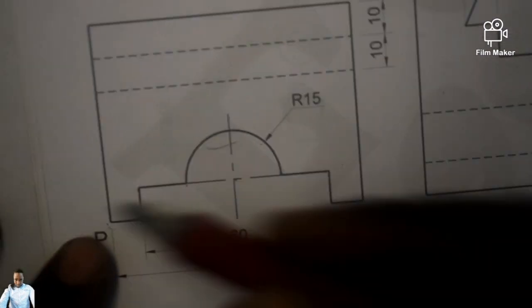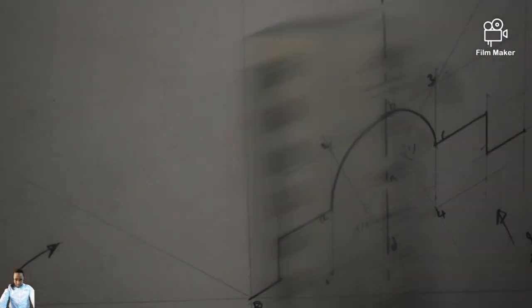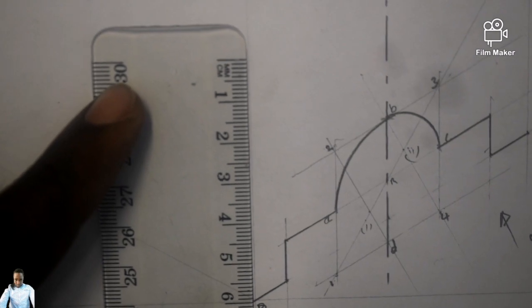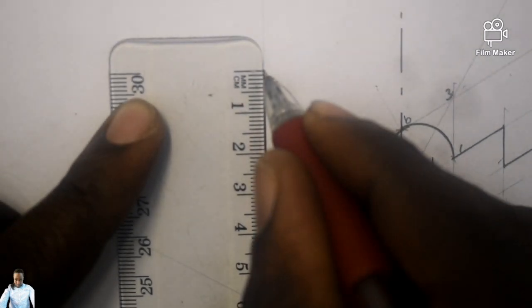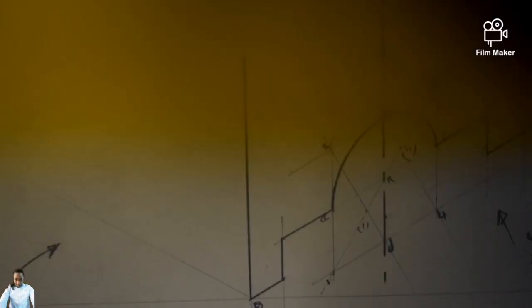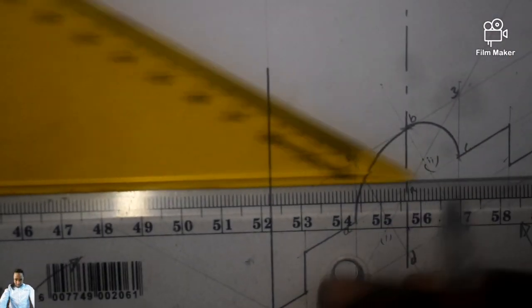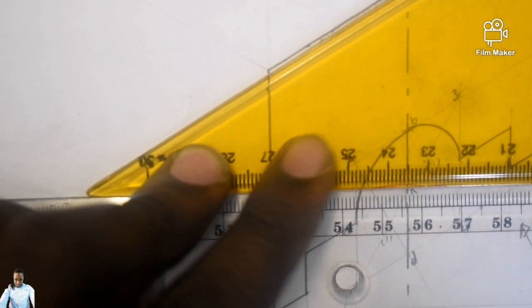After getting that, now let's consider the height. From here till there, we are told there is a height of what? Of 60 millimeter. I can go from there till there, 60 millimeter. So there is our 60 ending, and from there I can get this line, faint for now, and it's going to exist on my front view. And this one, since I know where it is supposed to end, I can easily draw it solid.